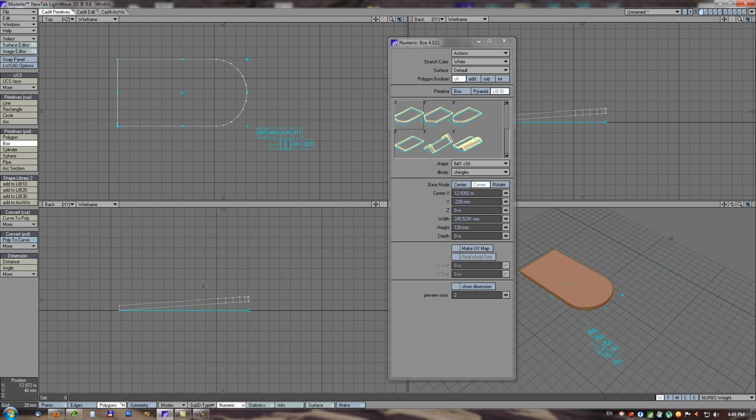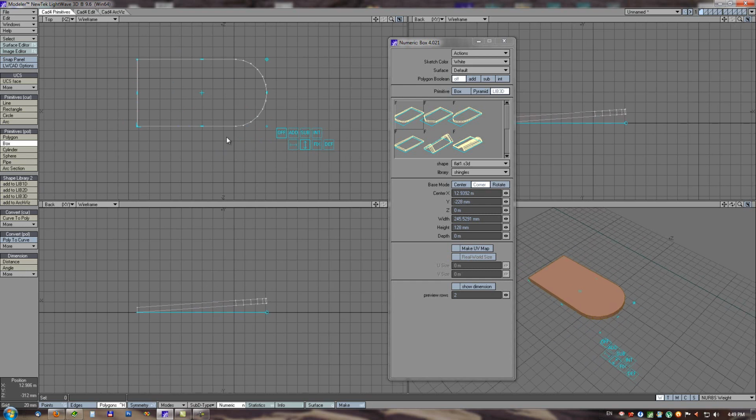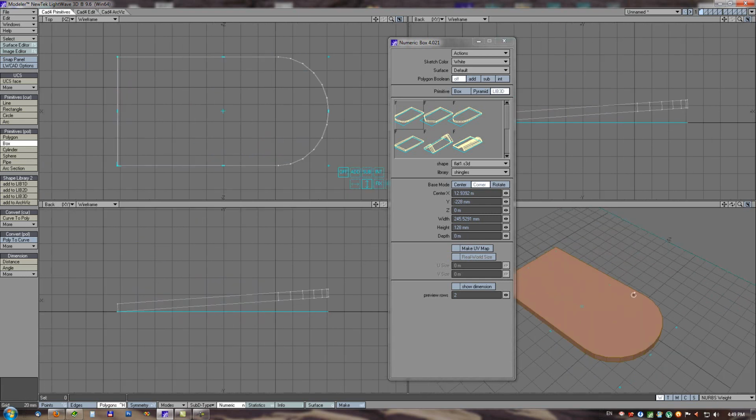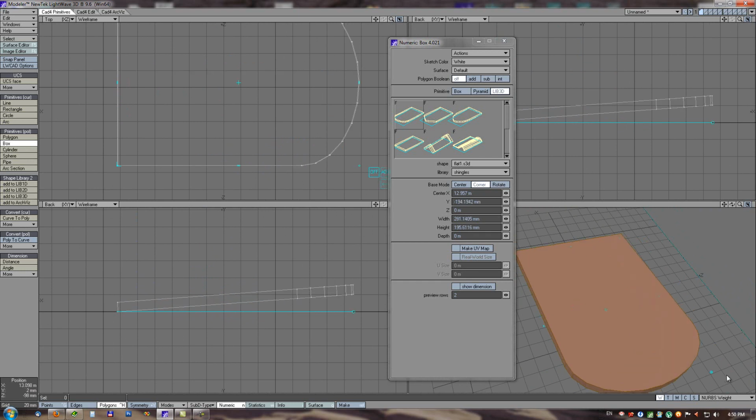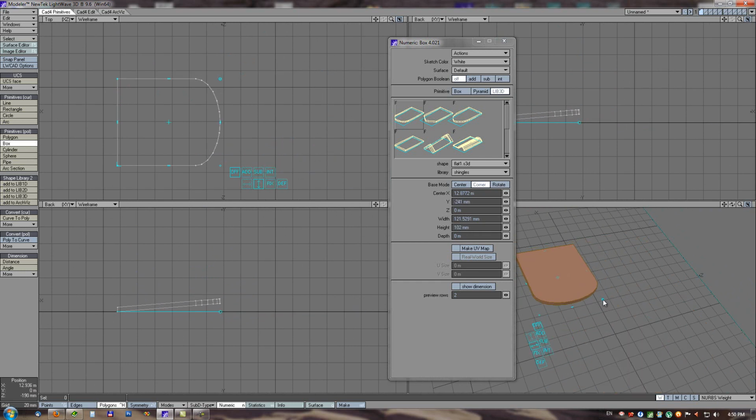And if we want to change the depth of this shingle, for example, just enable offset and we can scale it. With the 2D button we are back in 2D mode, and the depth of the object is always properly scaled. Okay, that's the 3D shape option for the box.